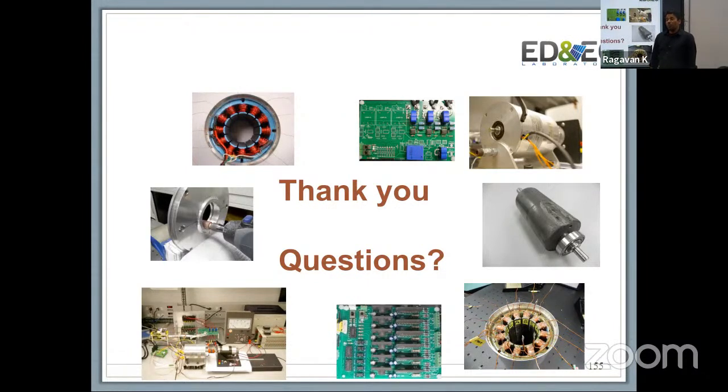But keep in mind, when you do something like that, your concepts of field-oriented control go out the window, because all of your Clarke and Park transformations are built on basic assumptions. If you do the full derivation for the transformations, you will see that it relies on symmetry. If you don't have symmetry, your controller has to accommodate for that. That was one of our selling points for this idea: you need to know where the fault is so that it can compensate.